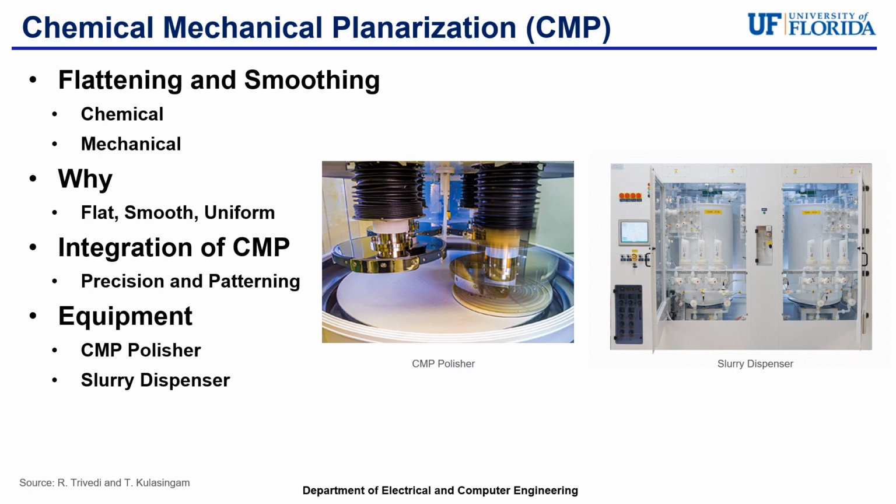As for the equipment used to enable CMP, there is the CMP polisher, which physically grinds down the surface of the wafer while also applying a chemical slurry that helps polish it. Another piece of equipment is the slurry dispenser, which supplies the polishing mixture used during the CMP process. The CMP process is one of the most important because it interacts with every other step of the process and ensures the reliability of the layers built on the wafers themselves for the semiconductors.